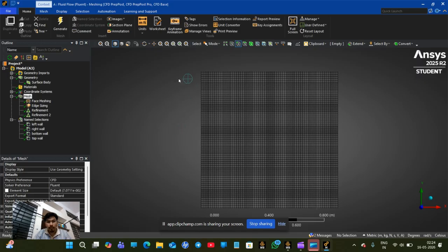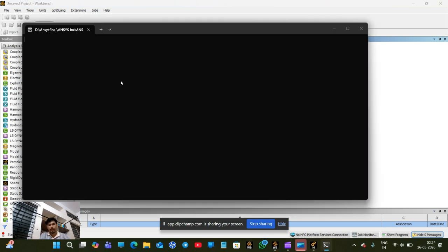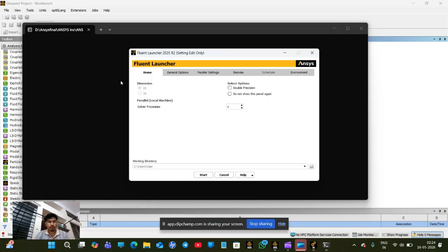Now I will go to the Fluent setup. We'll select double precision, 2D. Start.